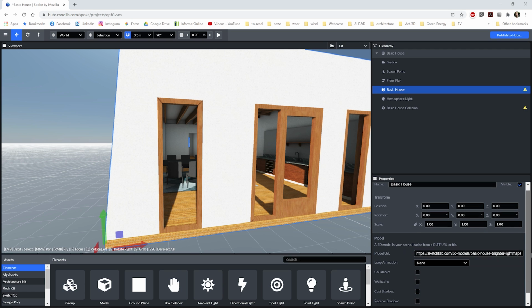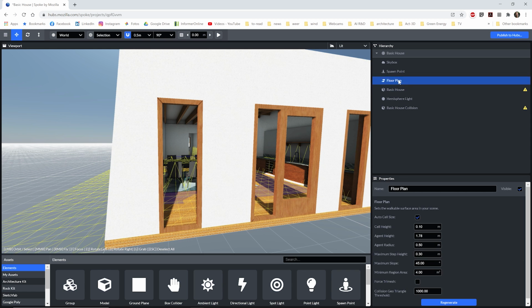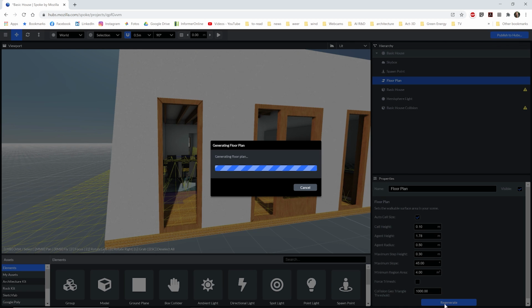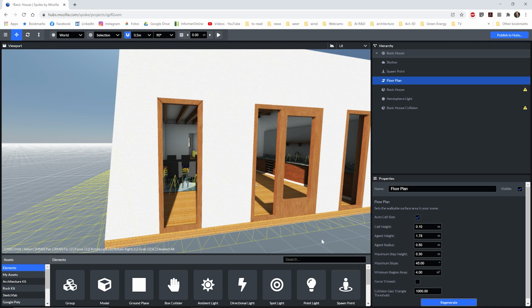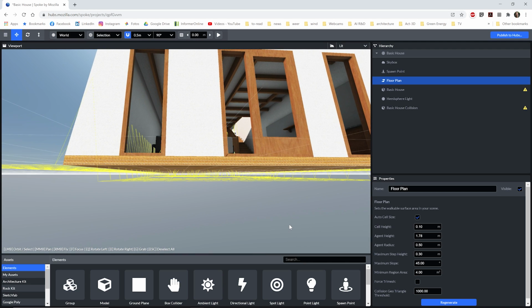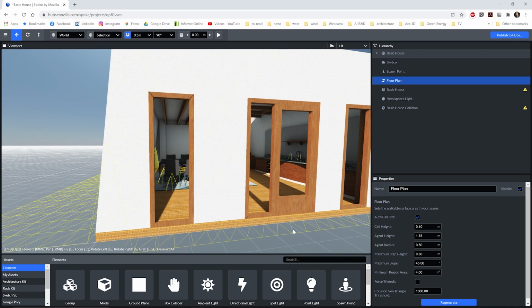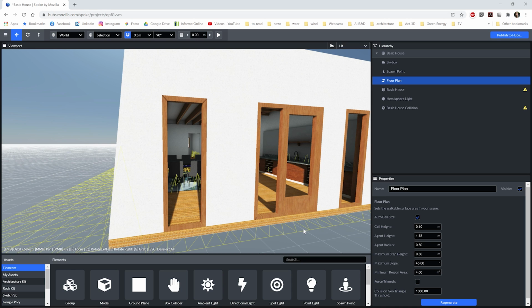For example, you can make an object with only the house's floors and stairs using your 3D modeling tool. And when you add the object to this project, it should be the only object with walkable and collidable options turned on. This will not only improve the performance of the VR experience, but it will also make it easier for people to walk through the house without bumping into furniture objects.